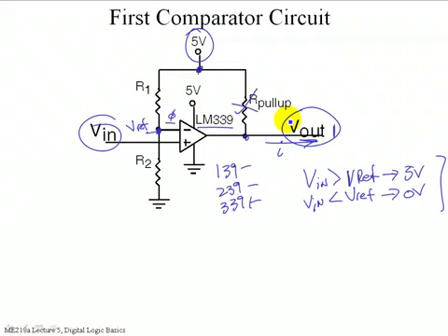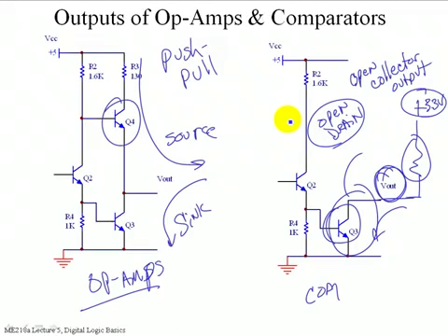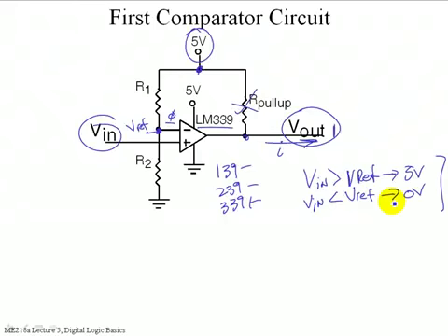Will I leak current until V out rises? Where would I be leaking current from? So I'm going to leak it from the base to the collector. But the base is only at 0.6 of a volt because the emitter is tied at ground. And if you use the diode model, which is maybe what you're thinking about, there's another 0.6 of a volt, so there's no potential to drive that up. So I'll save you, yes.